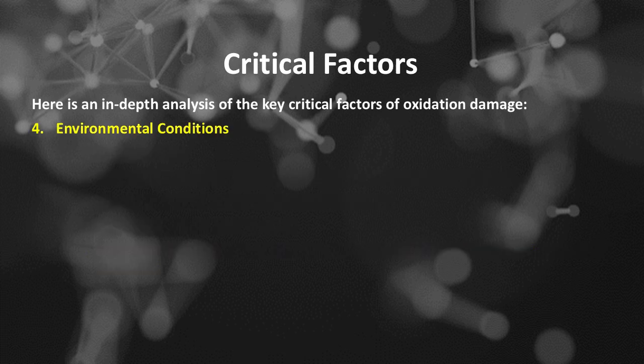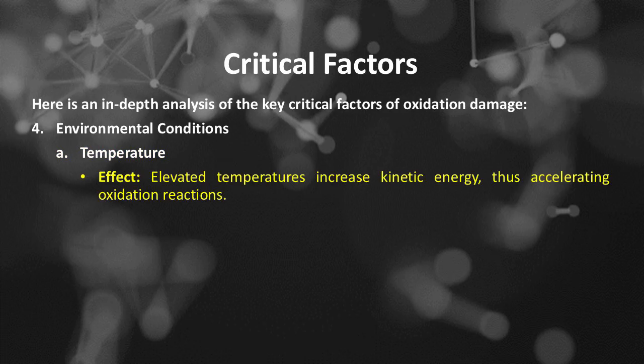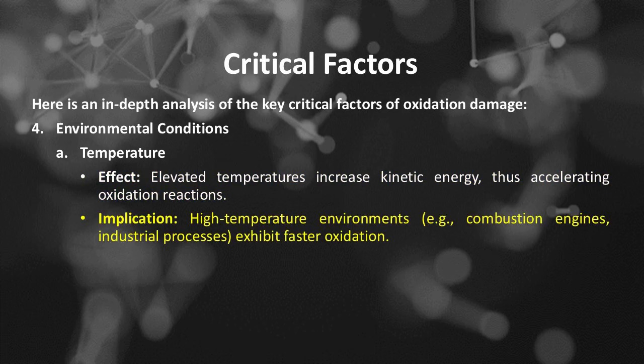Number 4 of the key critical factors of oxidation damage is environmental conditions. Number A is temperature. Effect: elevated temperatures increase kinetic energy, thus accelerating oxidation reactions. Implication: high temperature environments, such as combustion engines and industrial processes, exhibit faster oxidation.